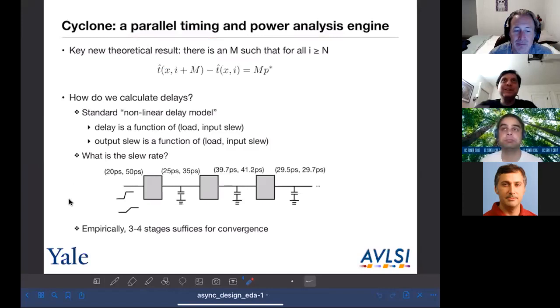And yeah, these are all the things that make the timing analysis much higher complexity, because you also have to go around multiple cycles. So your effective circuit size is actually much bigger, because the periodicity is not just one iteration. It's effectively like having a clock circuit that's been unrolled a whole bunch of times on which you need to do timing propagation, because you basically end up going through the same gate multiple times to get all the correct offsets. But yeah, so you would have to do noise propagation during timing propagation. That's the right way to do it. Yeah, that's a really good question.